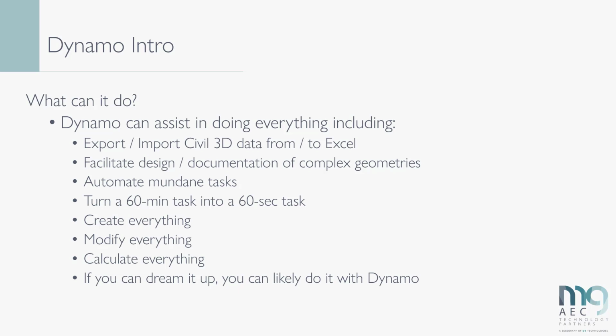Now, what can it do? So Dynamo can assist in doing many things. You can export and import Civil 3D to and from Excel, and have many scripts that select different points along alignments and things like that to push right to an Excel CSV that my surveyors can take in the field.